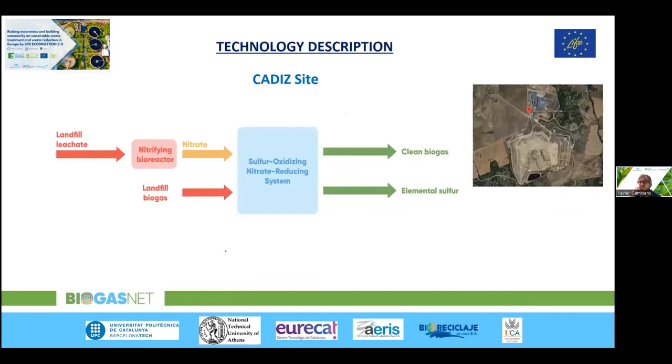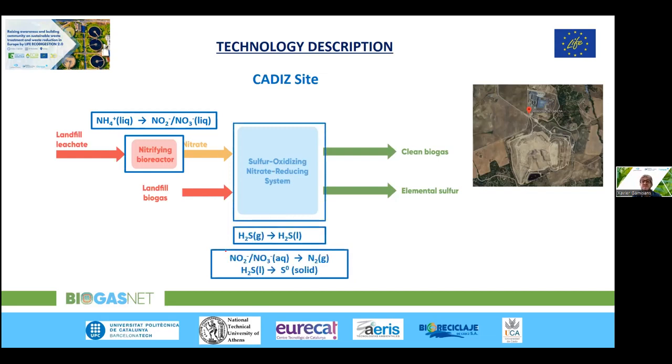Okay, we have been operating the prototype in Cádiz, in the complex of Miramundo Los Ardales, where the biggest landfill in the Cádiz province is. And there we installed the prototype with these elements: a nitrifying bioreactor, which collected some landfill leachate to produce nitrogen as nitrate or nitrite for the sulfur oxidizing nitrate reducing system.